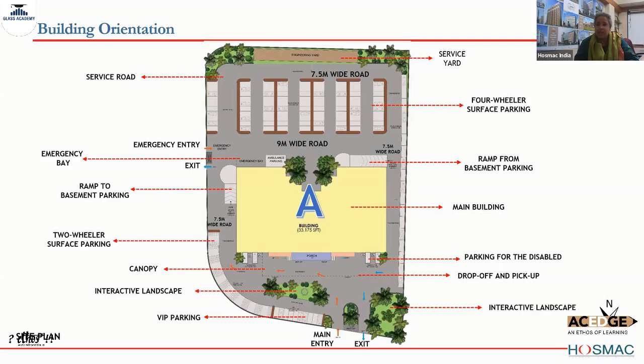We have tried to limit the east and the west, and the southern side we've tried to break it further and push the building in, so that the shading of the tall building onto the other surface would allow for sunlight to be cut from the southern side. Otherwise, the building can really heat up. It's better to break the facade of the side from where the sun hits.